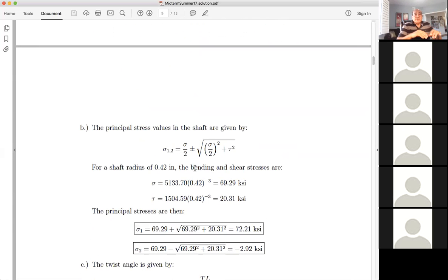And that brings me to the last part. The last part of the question was finding the principal stresses, and the principal stresses are another way to look at failure. When you see the term principal stresses, it triggers in our mind that we have a triaxial stress state generally, and we want to pick either the maximum shear, which is what we did before, or the principal stresses. The reason is always that failure is based on maximum shear or on the principal stresses.